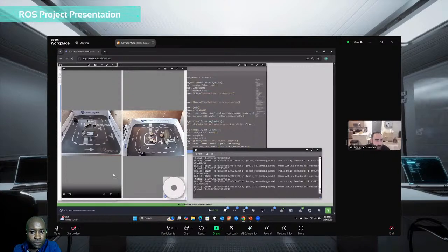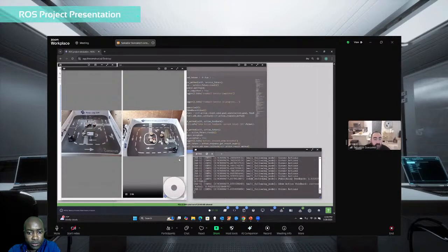If I narrate just a little bit about the decisions that the robot's making: there are basically two categories of the wall following behavior, which are normal and corner actions. The corner actions start when the front laser range, which is just a mean of a few of the indexes, registers that there's an obstacle in front.